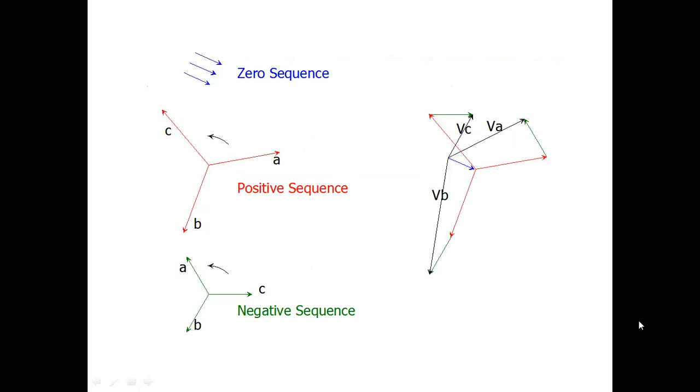This is the phase sequence shown here. It is the zero sequence component; the magnitude is the same and the sequence is zero. This is the positive sequence component, ABC. And third is the negative sequence component; the sequence is CAB. Now we can draw the phasor quantities: VA0, VA1, VB1, and VC1. We take the phase sequences, add them, and calculate the total voltage VA.